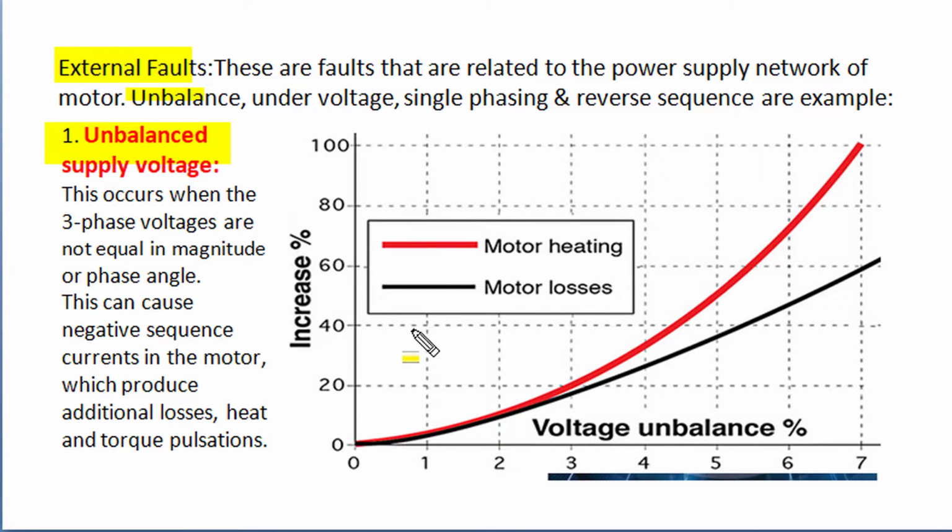This occurs when the three-phase supply has unequal magnitudes or other than 120-degree mutual phase angle. In that condition, if we analyze the unbalanced supply voltage, it has a negative phase sequence component, and that negative phase sequence component generates a reverse rotating magnetic field that has a higher value of slip, 2 minus s, on the rotating rotor winding of the induction motor. That causes excessive rotor current and rotor losses that also get reflected in the stator current and produce stator copper losses.